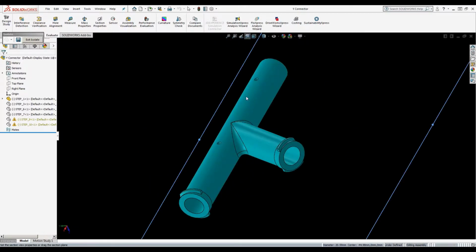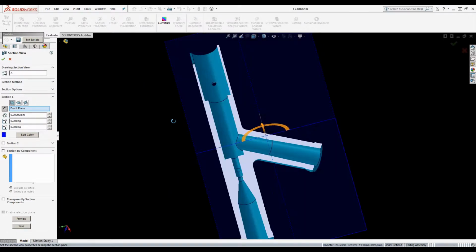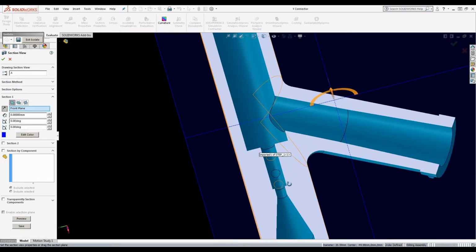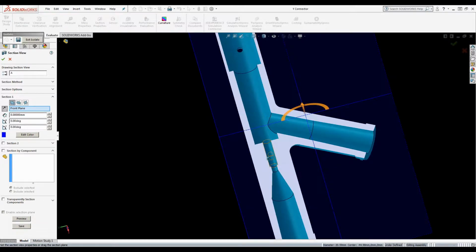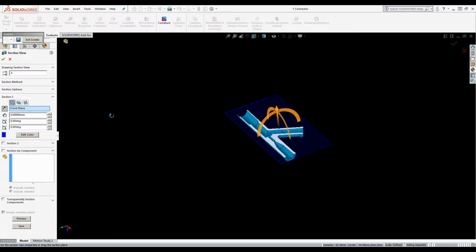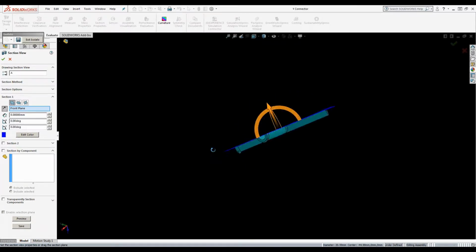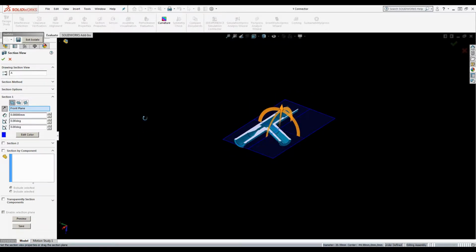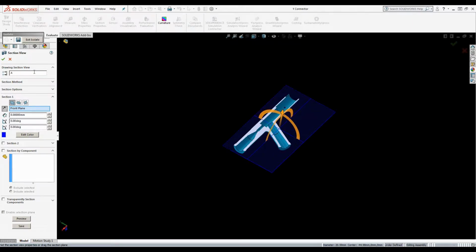So if we do a section view here, you can see on the inside of this part the unique shut offs that we have from this component coming in, shutting off on this pin, and then these small areas within the part, and then a thick section. So what I'm going to do is bring up the tooling and how we configured it and how the shutoffs look.